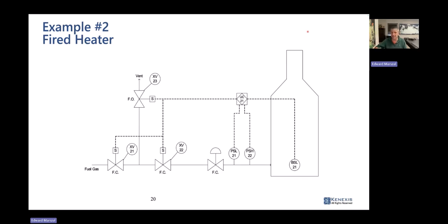I might send someone out with a portable gas detector to sniff the fired heater before you put the fire in the firebox. So there is a different mechanism that is intended to protect against that action in the fired heater case.